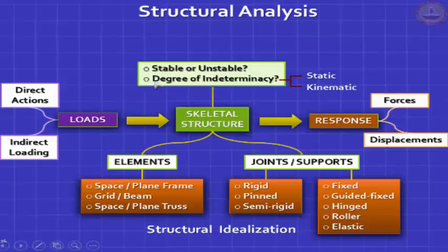And if it is stable and you want to use it, you have to decide whether the structure can be analyzed, so it's indeterminate or determinate. We've already looked at static determinacy and indeterminacy, which is in terms of forces. So your structure is said to be statically determinate if you can get all the forces by simply applying equations of equilibrium, which is called statics.